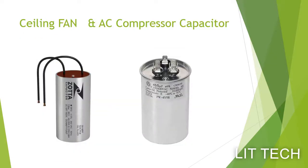We might have seen capacitors in many places like a ceiling fan and an AC compressor. In this case, the capacitor is used to start the motor. Is your fan running slower than before? Mostly it is due to the capacitor. The capacitance value in the capacitor might have been reduced after a while. In most cases changing the capacitor will solve your problem.